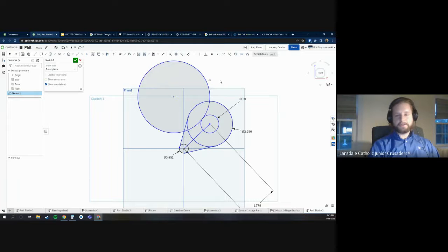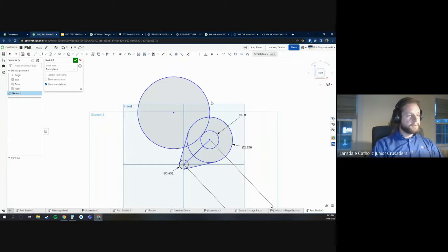So in this gear train, I'll reiterate, I have a pulley reduction first, and then I'm going to have a gear reduction afterwards. And I'm using the gear reduction because I have more torque now. I'm afraid that if I did another pulley reduction, I would slip with my belt. So instead, I'm going to try a gear reduction. And maybe we want to go from an 18 tooth gear to a, I don't know, 48 tooth gear divided by 20.